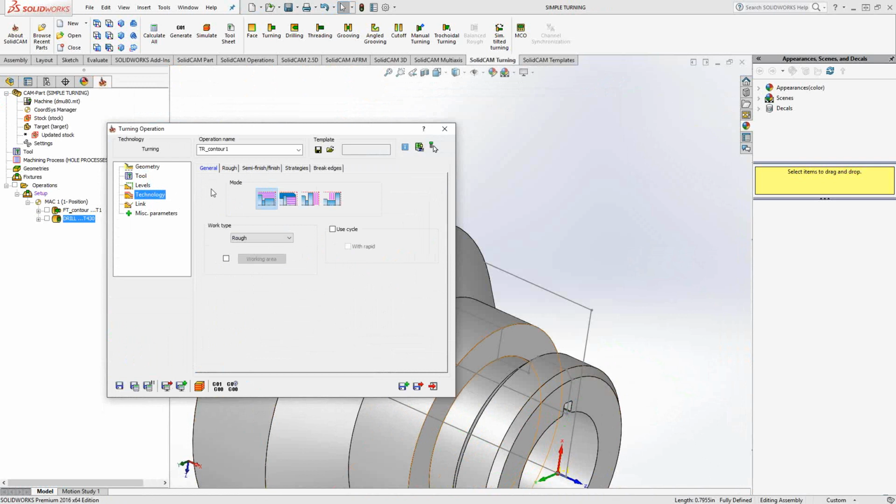I said at the beginning of the video, the turning toolpath actually lets you do the OD and the ID. So you can choose those modules there, or you can do the face front or the face back, meaning that if the tool was still oriented in that positive Z direction, I could use a grooving tool or a diamond insert or something like that that is oriented correctly so that I can do countersinks, chamfers, dish geometry at the front of the part. That allows you to actually change the direction of the toolpath as well. If you find that the turning shouldn't go in the axial direction but go in the radial direction, then you can just click on face front and use the same geometry to face in the radial direction.